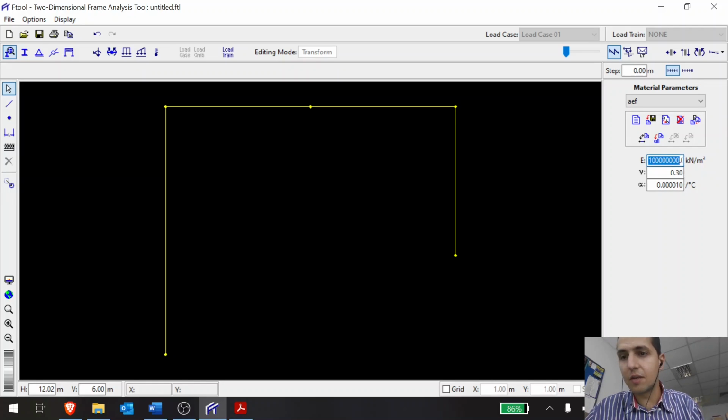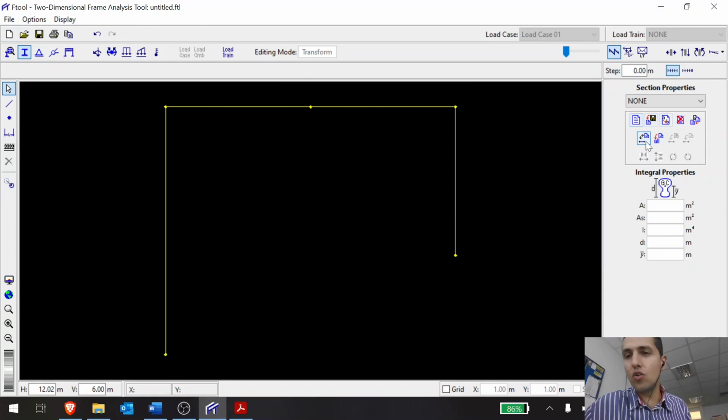I can say, for example, I want this to be 1 or 100 or whatever I want. And since for this model it doesn't really matter, I'm going to keep, let's say, 500. Any number here is fine. And I'm going to press all to apply the current material to all members. Okay? So once you press that, you should get these bars to have this material. So you're done with the material properties. You can move on to section properties. And here the menu looks kind of the same.